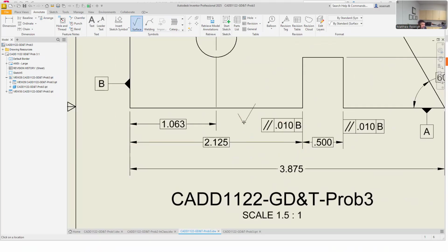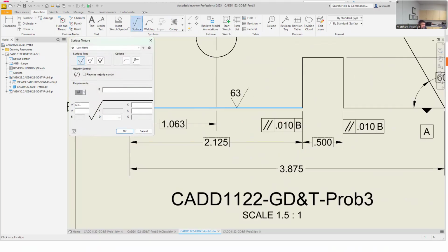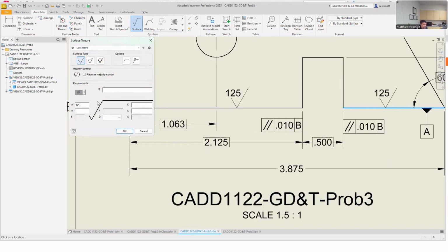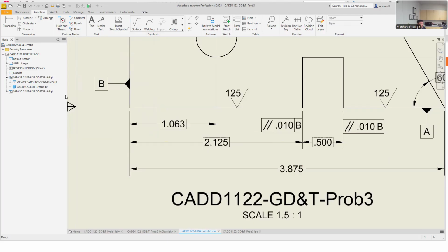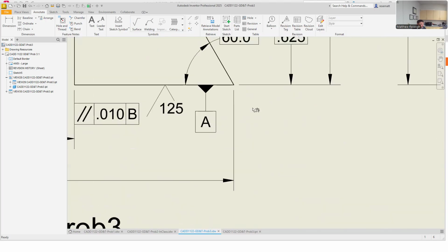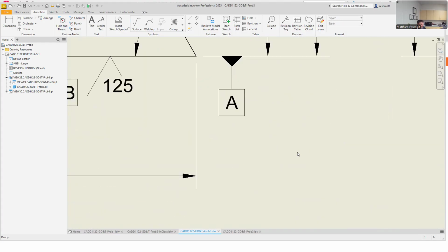And then I'll apply two more. I got this surface here. It's going to be controlled, highly finished. And I'm just going to add this one just in case someone and I could have a discussion around this if I needed to ask. So I might just move my datum feature. It's getting a little crowded. I'll just move it out to here. It's still performing the same duty.